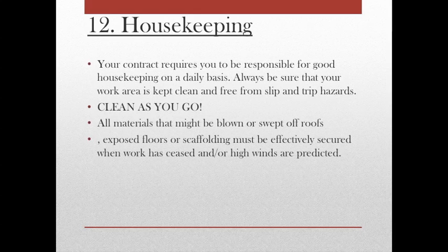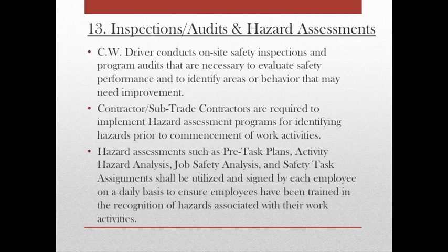Housekeeping. Your contract requires you to be responsible for good housekeeping on a daily basis. Always be sure that your work area is kept clean and free from slip and trip hazards. Clean as you go. All materials that might be blown or swept off roofs, exposed floors, or scaffolding must be effectively secured when work has ceased or high winds are predicted.